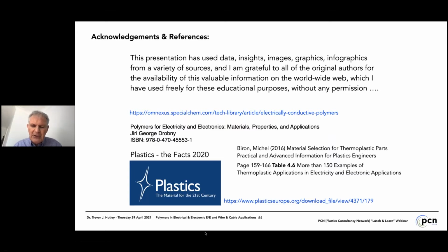And cross-linked polyethylene is an interesting kind of hybrid material because it's an insulating material that is applied. It's a thermoplastic material that's applied by an extrusion process to a wire or to a cable, and then the formulation of it includes additives which later, either in the presence of the heat of the extrusion or in the presence of moisture, cause it to cross-link and therefore become a thermoset material. So cross-linked polyethylene materials, as used in wire and cable, cannot be thermoplastically reprocessed because they become a thermoset material.